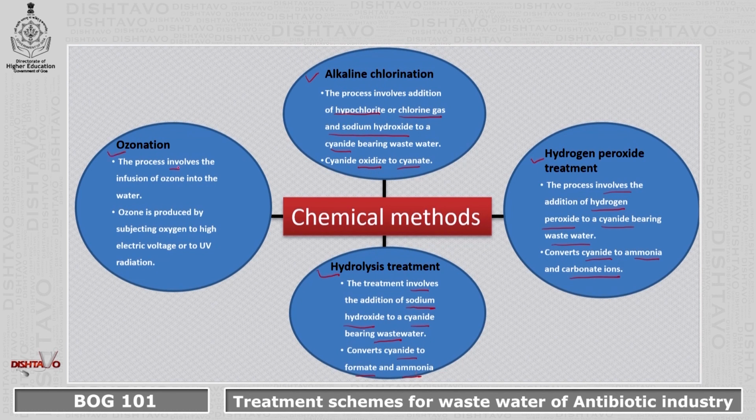It is the process which involves the infusion of ozone into the water. Ozone is considered an effective oxidant which will help to oxidize the organic pollutants present in the wastewater. During the process, the ozone is produced by subjecting oxygen to high electric voltage or to UV radiation.